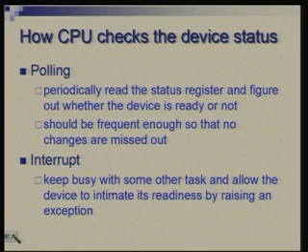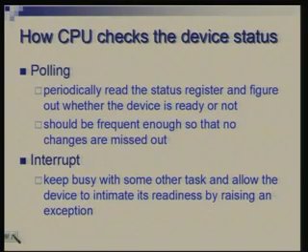Okay. So, if keys are being depressed at a certain rate, let us say at the rate of 5 keys per second, and you are checking only once in a second, then you are going to miss out. So, you have to check frequently enough, so that nothing is missed out. This approach is called polling, where you are periodically sampling and trying to see; you would read a status register, check a particular bit and figure out if what you are looking for is there or not.